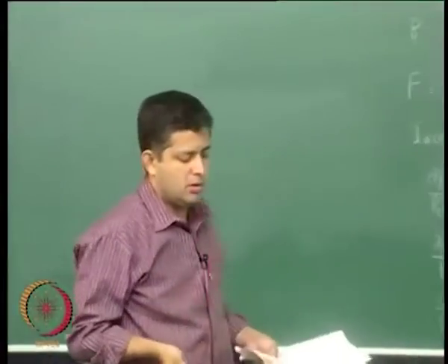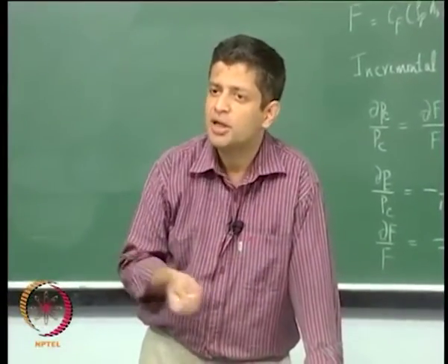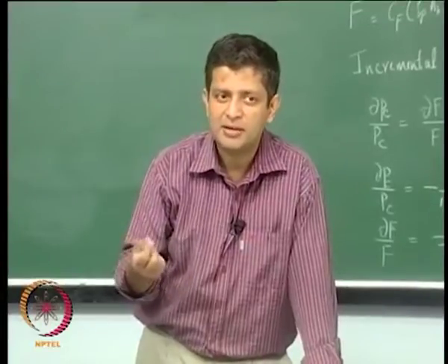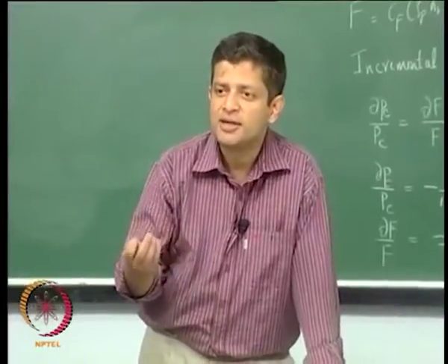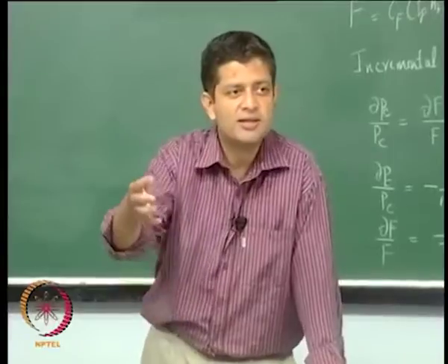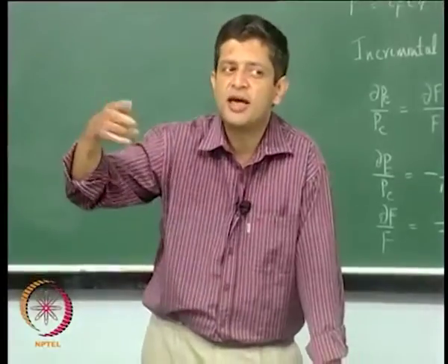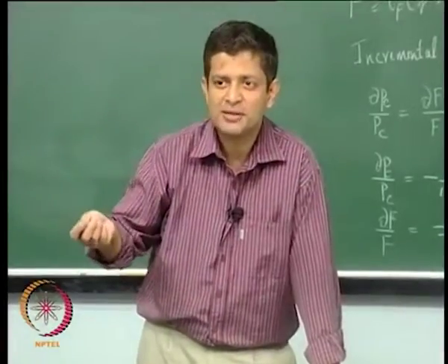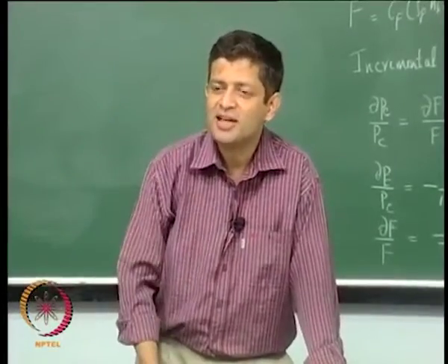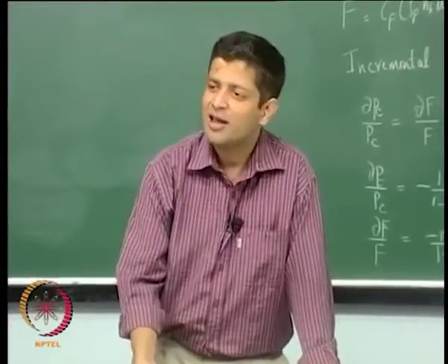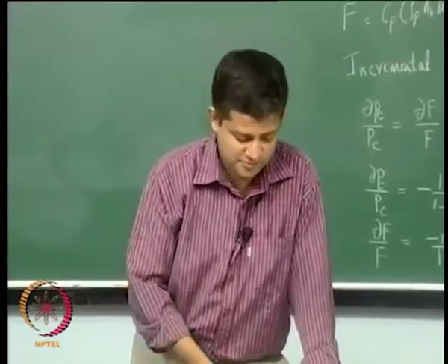Typically this throat erosion or deposition is a function of the burn time. If you have a large burn time, then you could have something like 8 to 10% increase in the throat area. If the throat area increases, then the pressure will drop. And you are also, in a sense, reducing the area ratio for the supersonic portion. So, it hits you in two ways. One is the drop in pressure, and the ISP will change because of that, and then again because of the expansion ratio being changed.